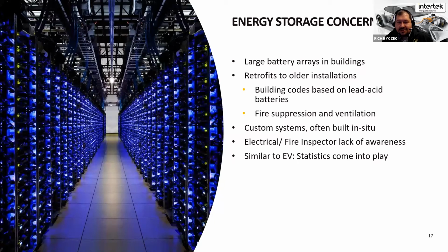Here we're talking about during normal operation of the lithium-ion battery, it's not expected to give off any gas, but under a thermal runaway event, we do expect volumes of off-gassing, volumes of smoke. Even if there isn't a direct flame involved, the volumes of smoke are not going to be covered or handled by a small circulation fan that was sufficient for a lead acid install. So a lot of the building codes are really concerned with these retrofit installations or even new installations that are built according to old codes. How do we address those additional concerns?